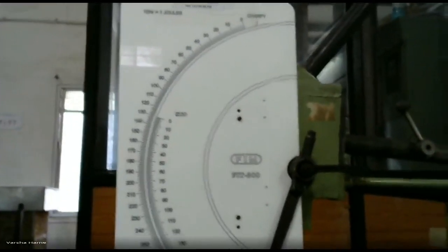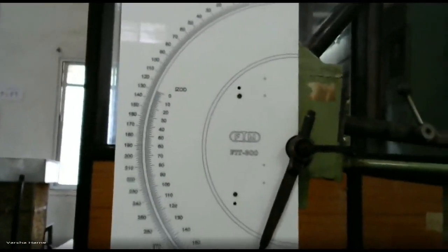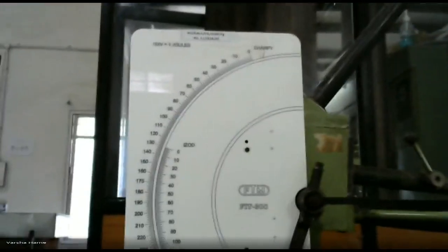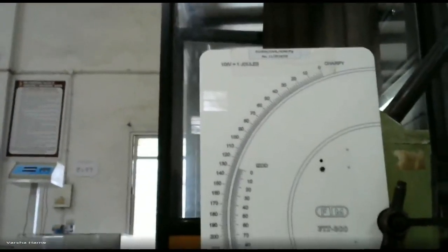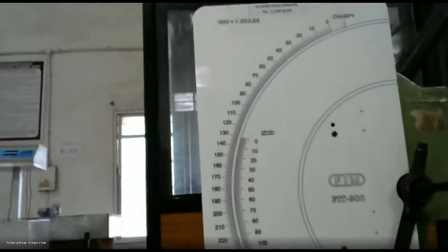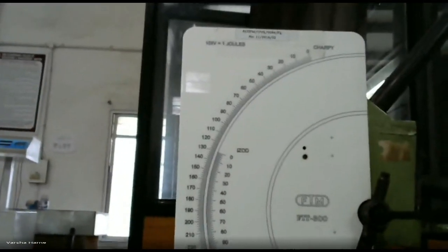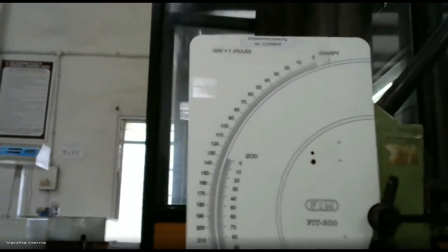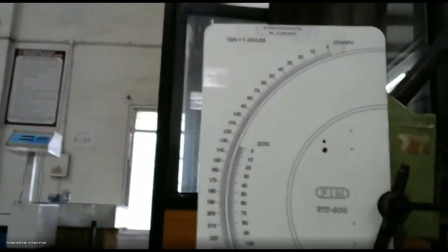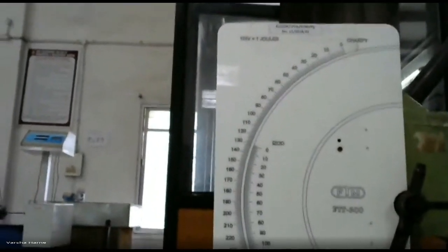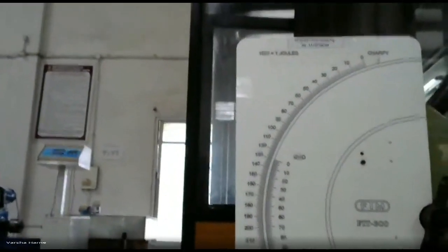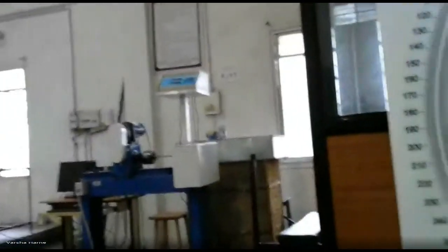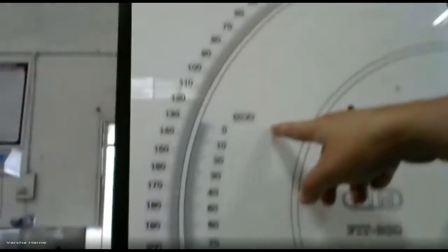Before that, we have to study how we can calculate our impact strength. We know what is meant by impact: we apply a large amount of force within a short duration of time, isn't it? And what is the basic difference between the Izod impact and Charpy impact? In Izod impact, it totally depends upon the position of our beam, whether our beam is a cantilever beam or a simply supported beam. So once we consider the Izod impact test, we have to set our specimen as a cantilever.